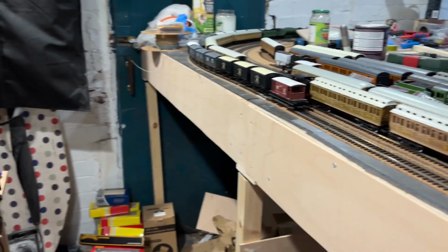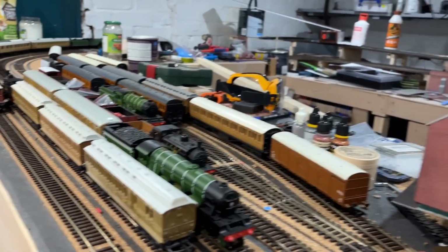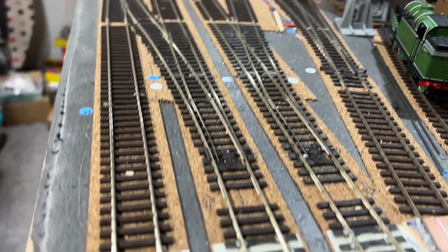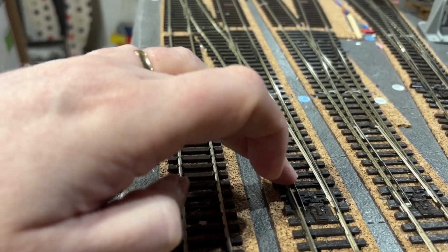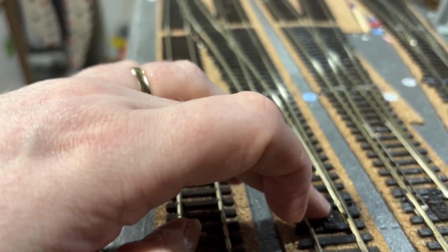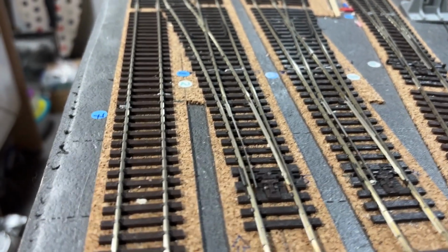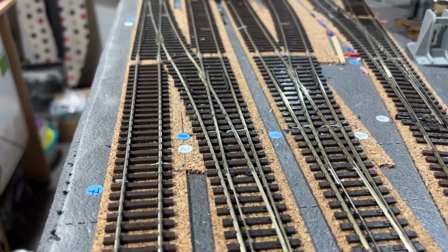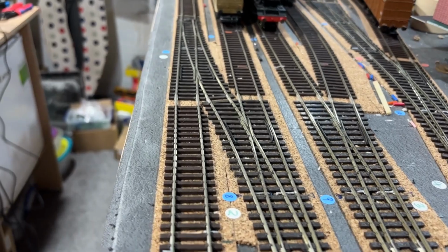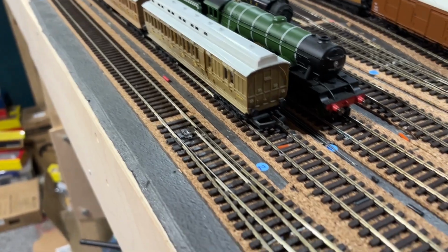The original idea was I'm going to put some switches and that's going to tell me where the points are. I thought about it a minute. It isn't. It tells me where the servo's pointing. It tells me nothing really about the point blades. I can imply where they are from where the servo is, but I don't actually know. And if I don't actually know and I'm implying it, and I'm going to have to set up a load of switches, and calibrate a load of switches, and maintain a load of switches to make sure they stay in calibration and don't move and get adjusted, why don't I not have the switches?